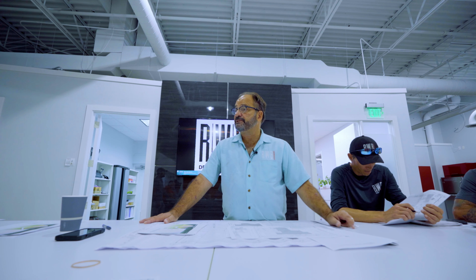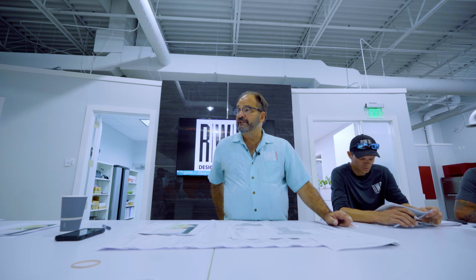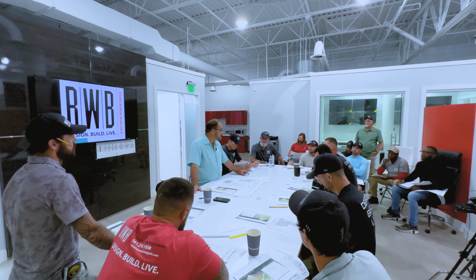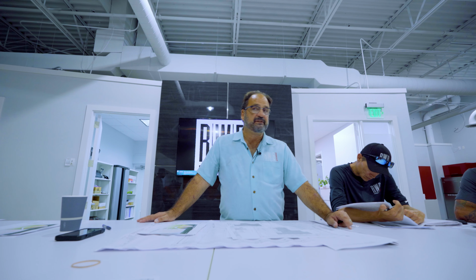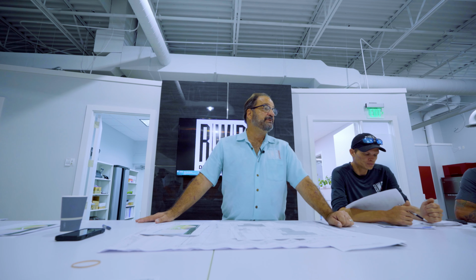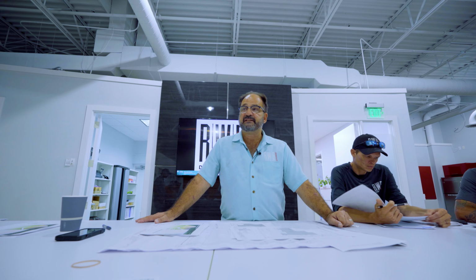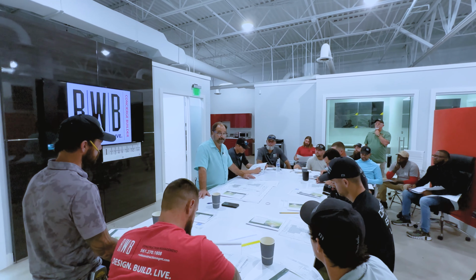For example, the exfiltration field that's under the driveway. We have 18 inches of rock under the driveway, okay? You have to make sure those things fall within the clearance you have for the driveway. If they don't, you go back to the civil engineer, okay? All the details he's giving you are based on his calculations. If that changes because of a field condition, you have to go back to the engineer, okay? Don't assume anything as far as size. Don't assume anything as far as detail. Follow the details that are given to you on the pages preceding the civil plan.